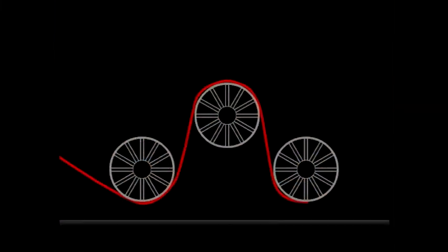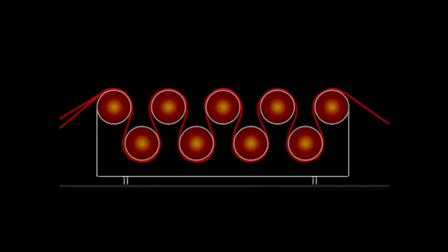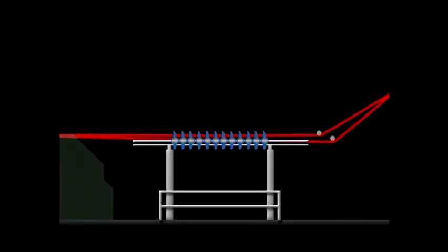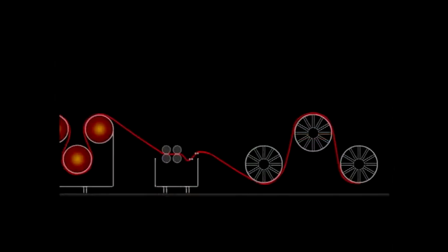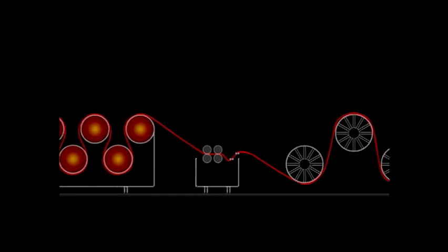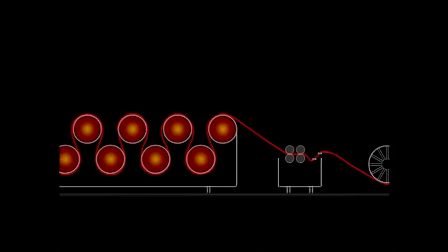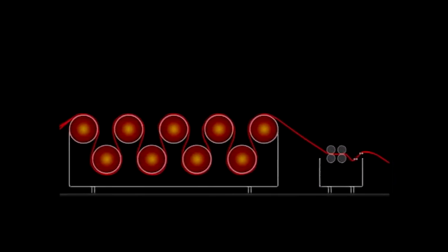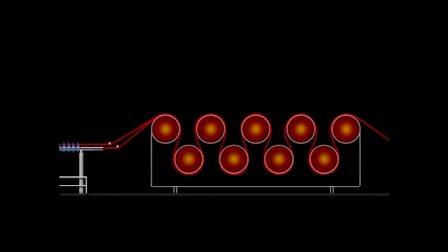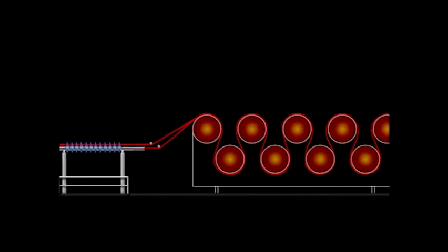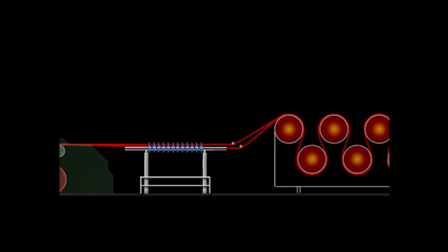The slasher is composed of a section beam creel, sizing boxes, drying section, yarn separators or bust rods, and headstock. A pre-wetting box can be located between the creel and the sizing boxes. The sizing boxes apply the chemistry that encapsulates the yarn. Benefits include gluing down hairs, yarn strengthening, and lubrication, which protects the yarn and loom parts. During this process, it is extremely important that each end be kept separate and parallel to adjacent yarns.